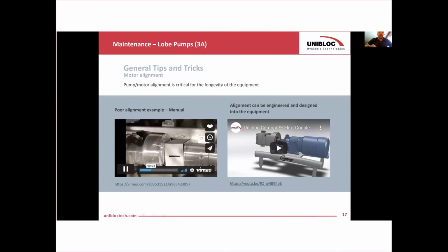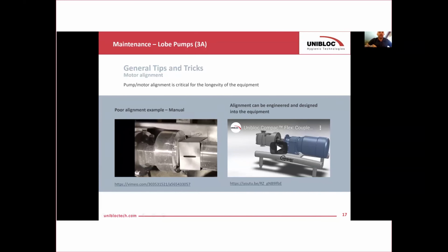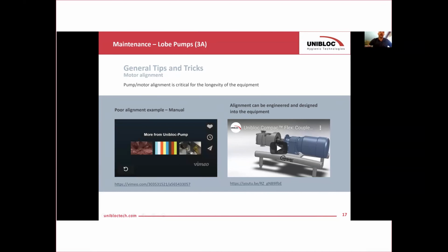On the left-hand side is the motor, and there you could see the motor was vibrating pretty heavy. That will then lead to bearing failures of the pump and create a higher repair cost.